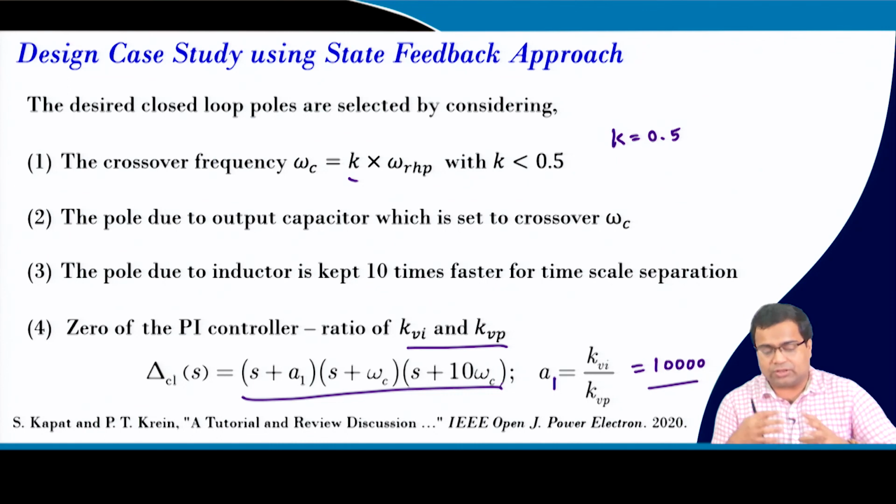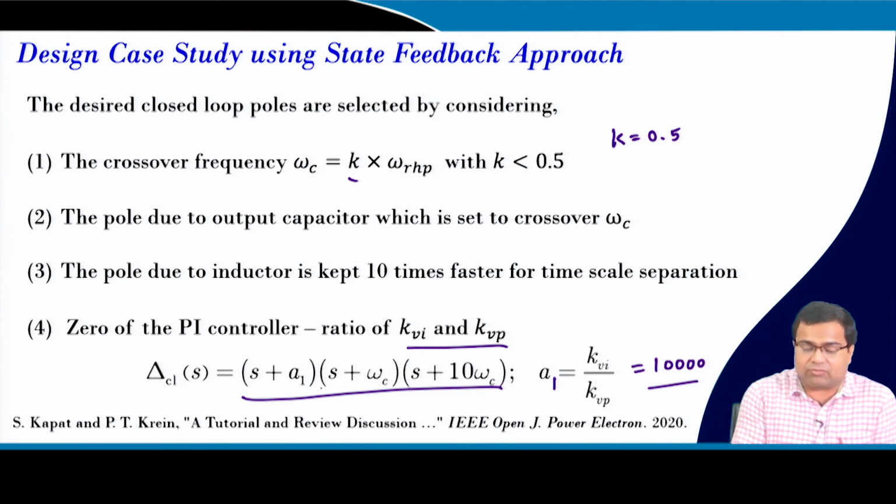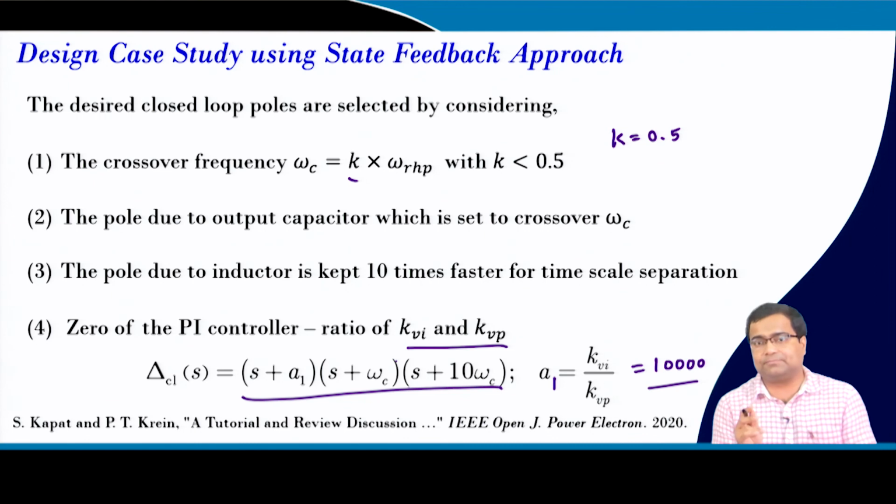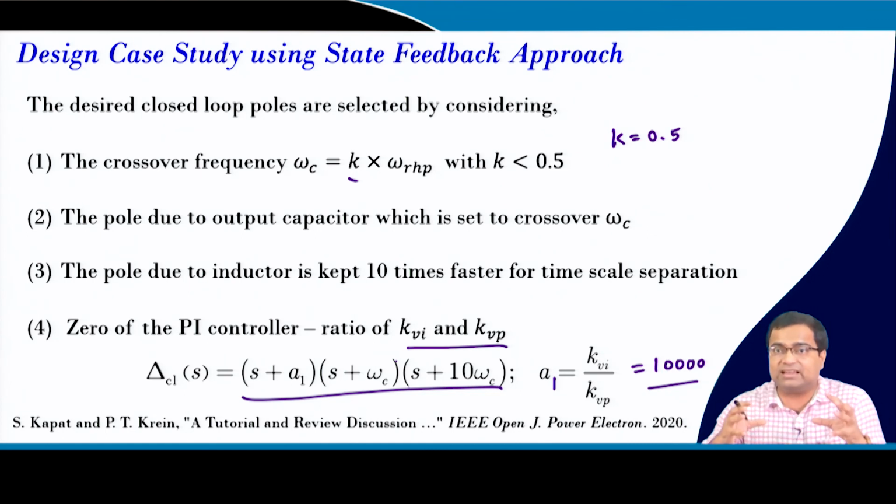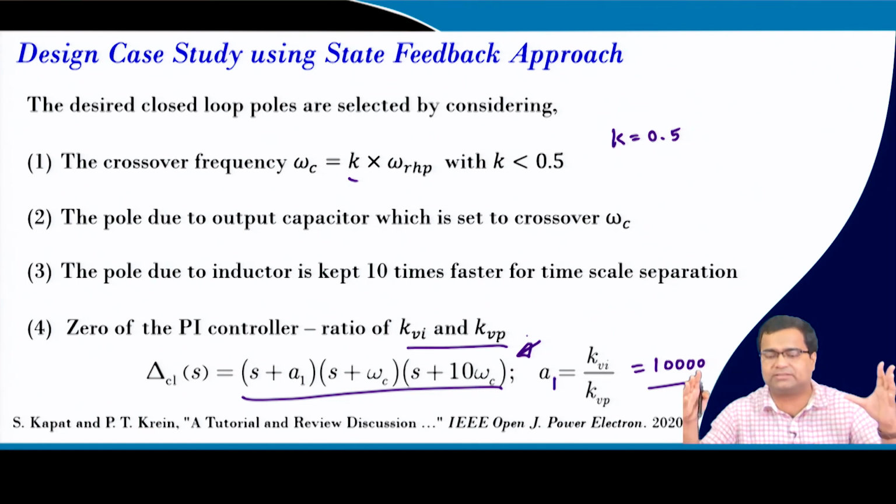Okay. So, here we are only considering a current loop gain, which you may not need to change in analog control. In fact, in analog control we will use offline design, because we generally do not do real time tuning. With offline design, in this state feedback approach we can simply set a current loop gain, and this approach can improve the performance much faster as well as much better, because there is less overshoot compared to the traditional output feedback approach. Okay.